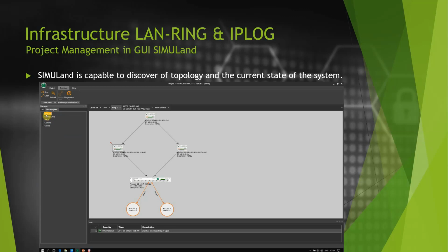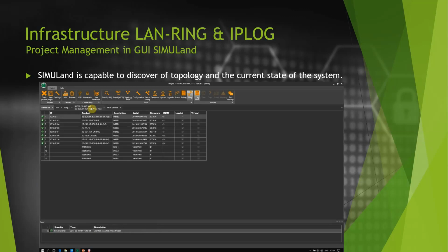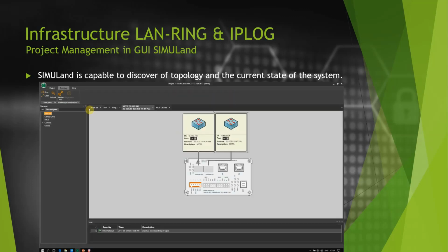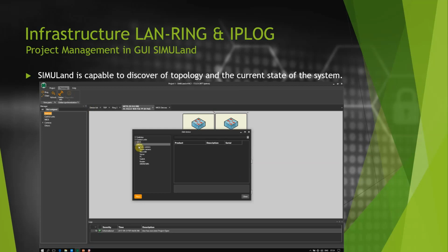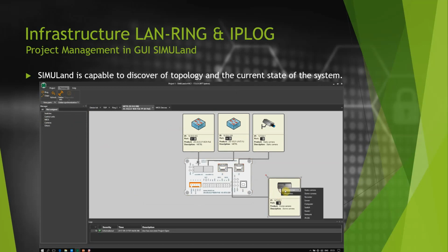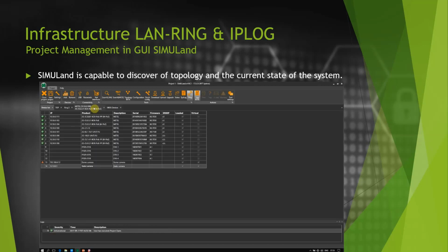Third-party objects such as cameras, servers, computers, but also all METEL devices are added to the project using the Add tool in the main taskbar, or by right-clicking on the device port at the lowest level, Detail, using the right button. You can directly assign the device without the need for a manager. If you add a device using the Add tool, you must place it from a manager and then connect it to a given port. For this object, it is also possible to change their icon. Deleting a device is only possible from the device list.